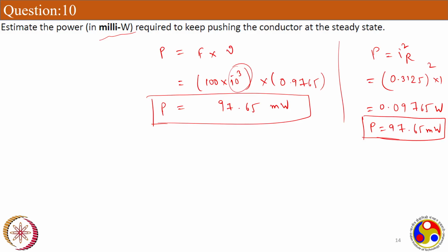Whenever you place a conductor in a magnetic field, in the presence of the magnetic field, a voltage will be induced in it. How do we find the direction of that voltage and the direction of forces? I hope you are now clear about what kind of rules we will use. The left hand rule is always used for calculating the direction of forces, and the right hand rule is always used for the direction and polarity of the voltages.